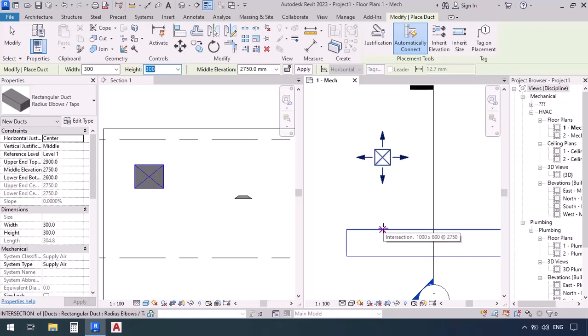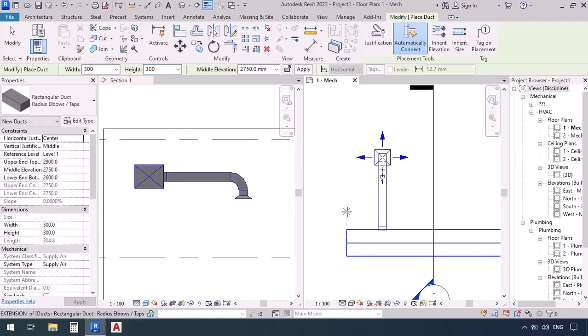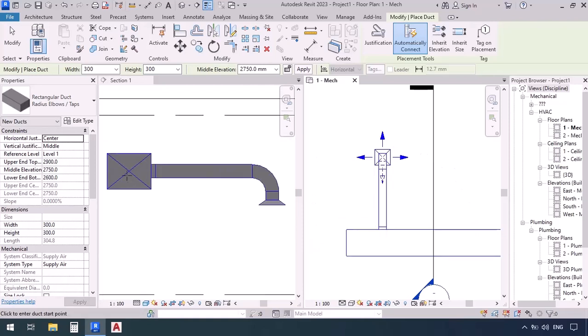Also, if you noticed, you can see that the terminal becomes highlighted, but we no longer have any central dash lines. Let's do it again. This terminal is black, and now I'm going to move the mouse along the outer line of the duct, and then suddenly the pointer disappears and highlights the terminal. This is actually an indicator for being right along the center of that terminal. So now first click and the second click right on the axis of the terminal.